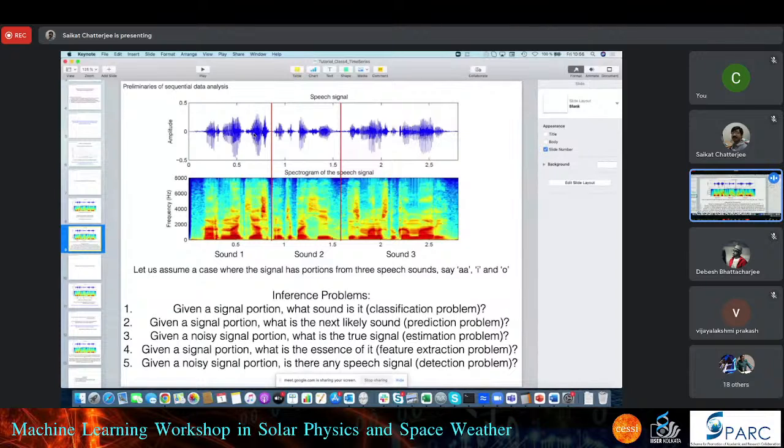Okay, but silence means I don't have to code this portion and send it through the channel to your mobile phone. I just have to tell that there exists a silence for this many microseconds. That's it. I don't have to code all the values of the silence, because silence is almost zeros, right? There is no need to code them and send them to the other side of the channel, because you are simply losing channel bits or your information resource over the channel. Because at that point of time, somebody else can use the channel and can talk. That's called multiplexing of the channel.